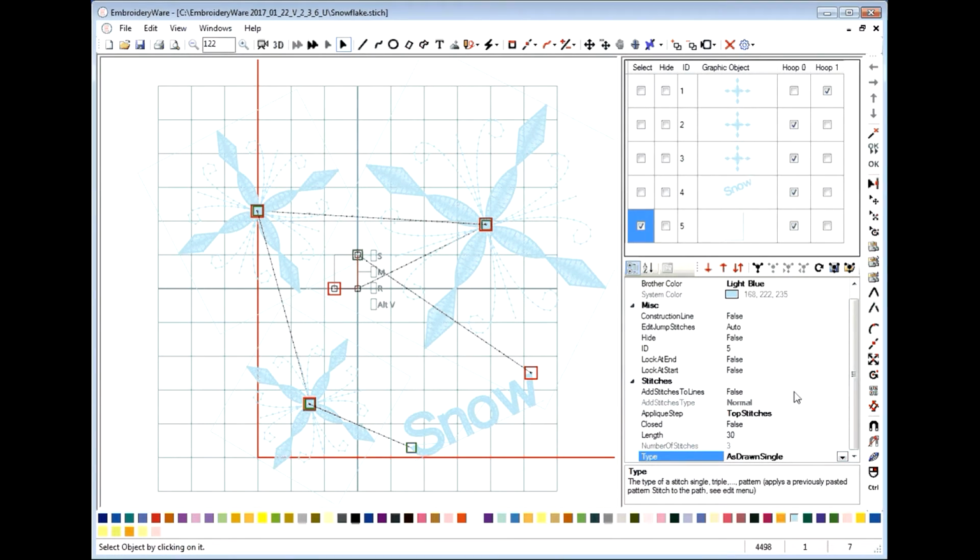And we don't want to add any stitches or lines. This is going to be a big basting mark like this, and we'll use the center point as our alignment mark. What's important about the alignment mark is you want it to be repeated in both hoops. So we're going to click both of these marks, and this mark will be put in the first design and in the last design.